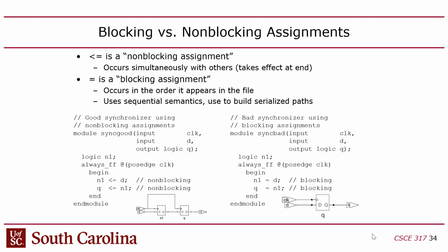By the way, if you guys ever look at VHDL, the way they implement this is, instead of an always, they have something called a process. It's analogous to the always. Same idea, has a sensitivity list, and you can use if statements and loops and that kind of stuff, case statements. So it's kind of the same idea.